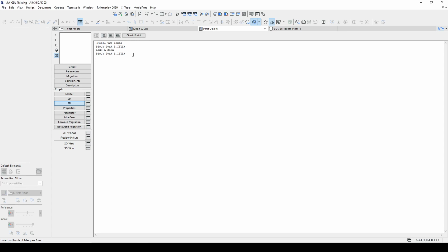Now, I am going to do a del 1. This del 1 essentially takes away this x transform. I'm going to do add z 2 feet. If you don't put the foot or the inch symbol, it's going to default as meters. I'm going to draw another block. And let's see what that does. I'm just going to use the 3D view.